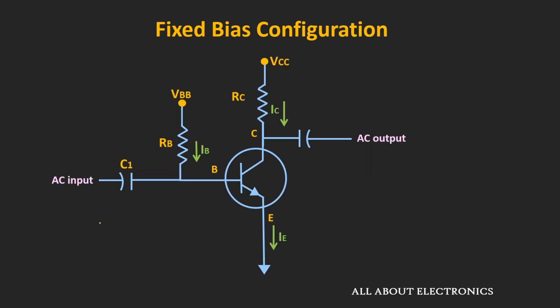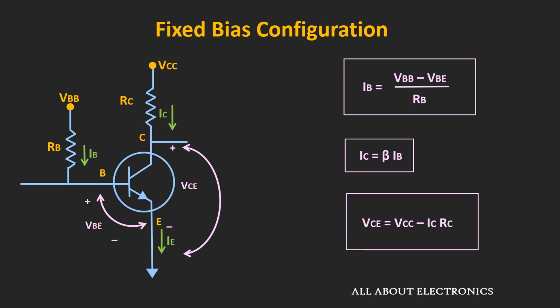In the earlier video, we have already derived the expressions for the base current, the collector current and the voltage VC for this fixed bias configuration. Now during the DC analysis of the circuit, usually when we write this collector current, we write it as IC equal to beta times IB. But actually it is given by this expression. For silicon transistors, as this reverse saturation current is in the nanoampere range, the second term is often neglected. But here, as we are interested in finding the change in the collector current due to the change in this reverse saturation current, let us also write down the second term.